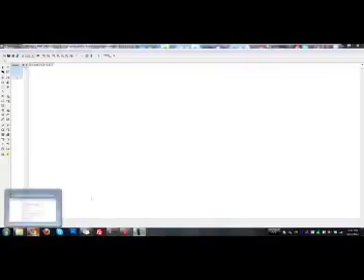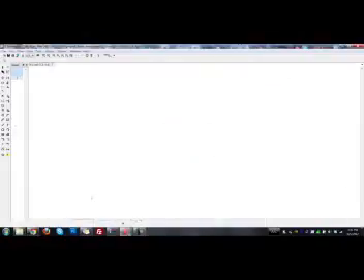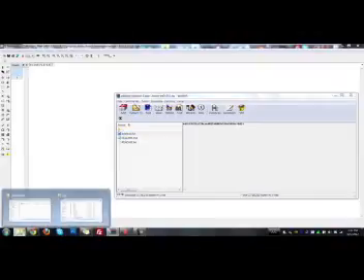It's useful in this case because we want to use a particular component, but it's good to know how to add an external library in case you find other open source libraries online that you want to use to add component footprints and schematic parts. If you go to the Adafruit GitHub page, I'll add a link to this in the video description, you can download the zip file of the Adafruit library. I've already done this. So if you open up the zip file, there's adafruit.lbr.